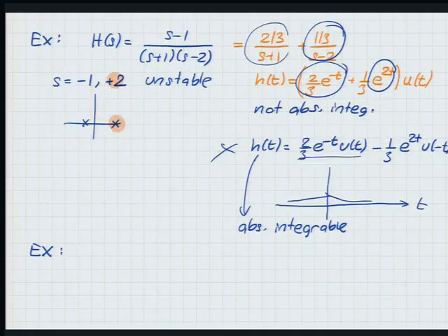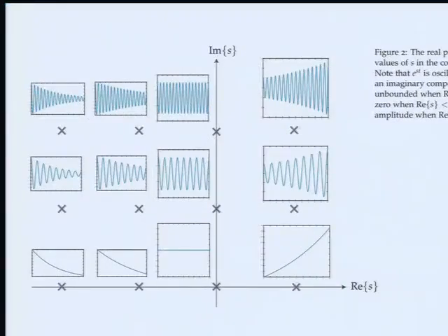So how is that so? Why do you think that is the case? Yeah, it may not be clear by looking at my famous picture why that's so, right? Because you have poles on the imaginary axis here, and the impulse response contains these things that keep ringing, but they don't go to 0, right? But they don't explode either. So why should I consider this to be unstable? Bounded input, bounded output, right? So I don't see any unbounded growth here.